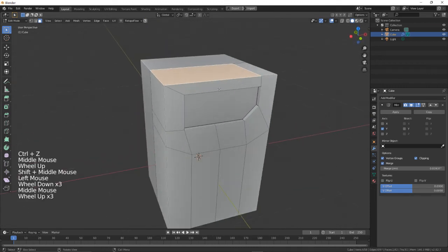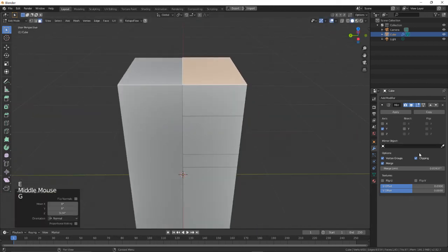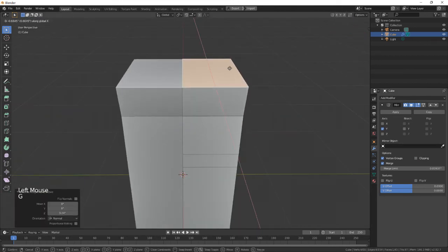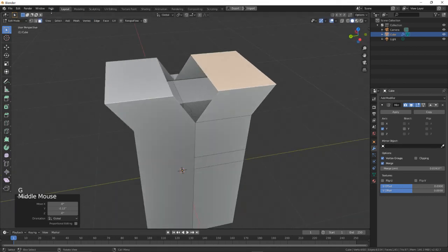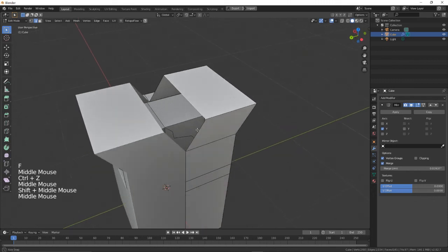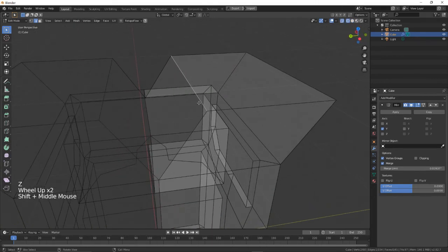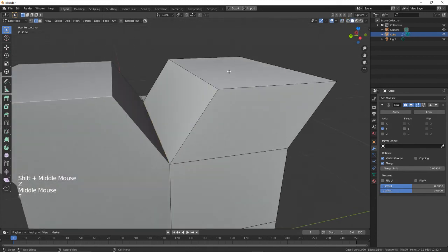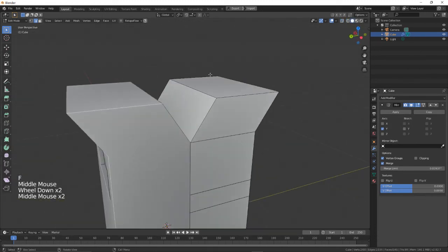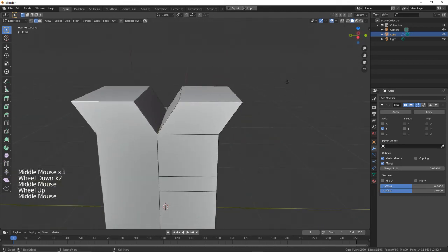Apart from that, you also have a couple of functionality things from Loop Tools. So if I extrude this object out, turn off clipping within the mirroring, move it over, and let me just quickly fill in this area. The way I fill in this area is I click this edge right here and press F once, and through the F2 add-on, it fills in a certain area, sort of like a ladder shape going down.